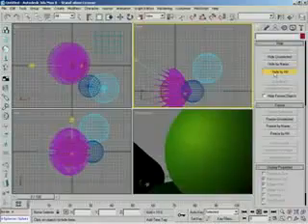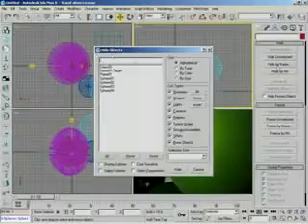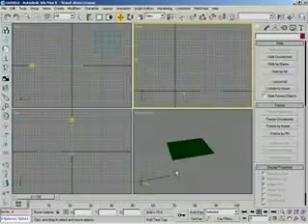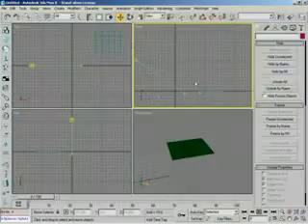Don't write this off. There's a couple things here I really do like outside of just selecting something. What if you'd made a car engine and you'd modeled every little bolt that's in it, and they were all named bolts or whatever. You could say hide by name. Come up here and type BO for bolts, and you would have all bolts selected. Or SP, or in this case, he's demonstrating it with sphere. And then we could say, okay, let's hide all those. They're gone. But we still have our plane here. We still have our light here. Which in the case of such a highly detailed model might give you better feedback in your viewport, might keep from slowing down your render. There's a lot of reasons you can do this.